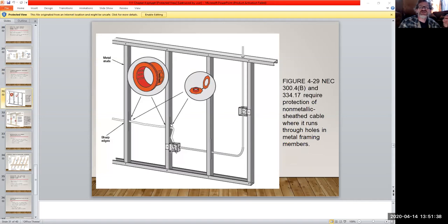But always watch. And with these guys, why would you have to have a little nylon plug like that, right? The reason being is because if you have the metal, you're going to have the sheath cable sitting on those edges. And over time, vibration and whatnot, your sheath cable will start to slice.